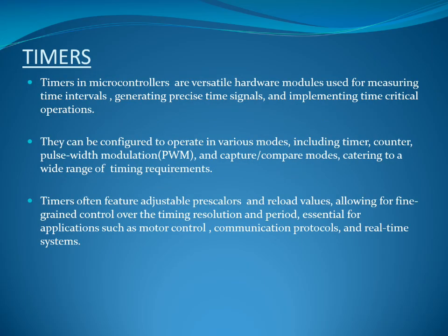Let's come to the timers now. Timers are indispensable components in embedded systems, acting as precise timekeeping devices that enable accurate scheduling and control of events. This allows the embedded system to perform tasks periodically, create precise delays, generate waveforms like pulse width modulation for motor control or dimming LEDs, and even serve as the basis for real-time operating systems by providing system ticks.